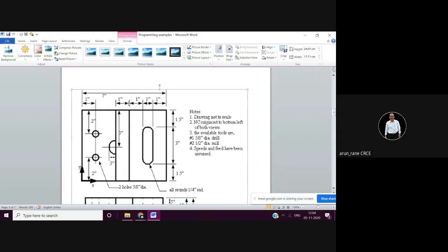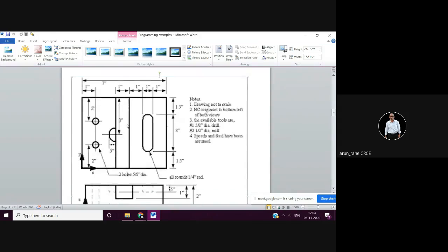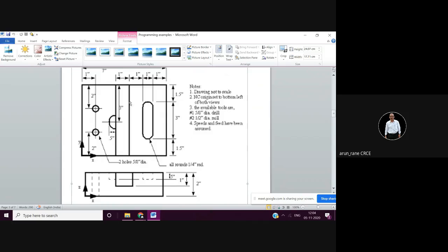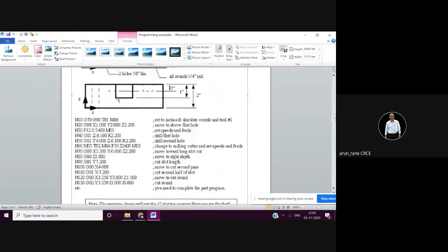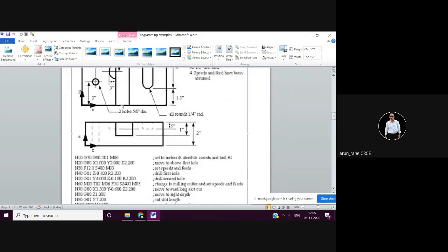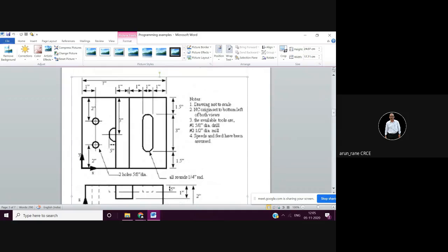This line is a 3 inch line and this is 4 inch. So this is 4 inch from here. That means what is the size you are going to get? Obviously plus, isn't it? Obviously plus. Yes, if you would have used cutter diameter compensation G41, he should have used G42, meaning the cutter is going along the right side, and then he is moving and coming back along the right side.